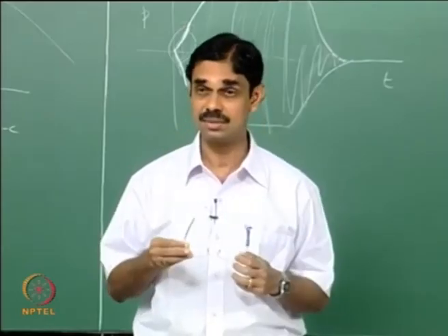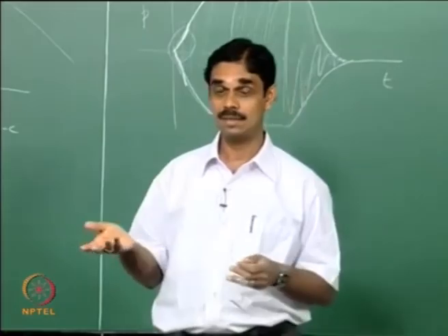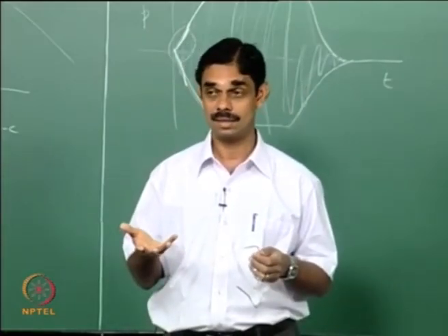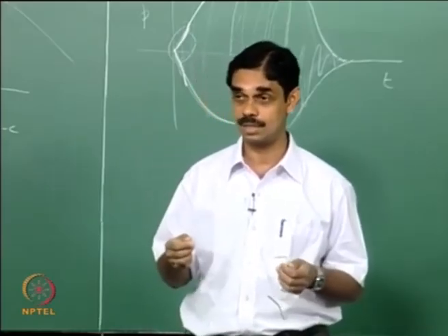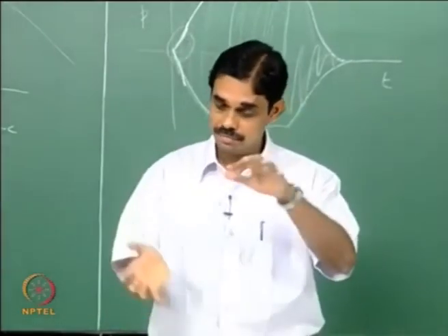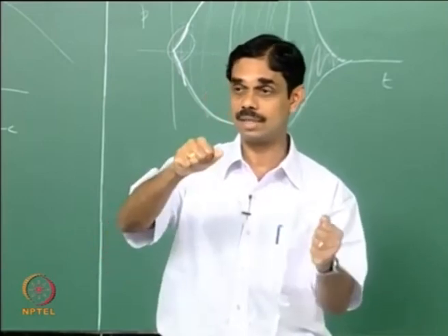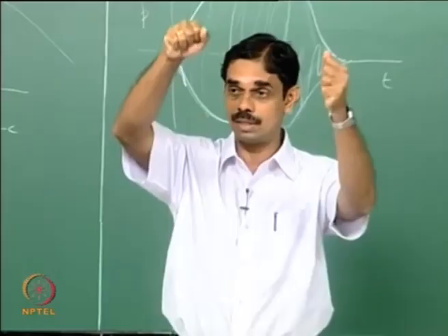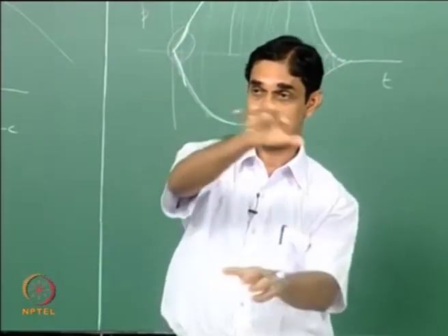Now, where to place the transducers, we would like to measure them at a pressure maxima. So if you have it at the end, then you will always have a pressure maxima, and therefore you will definitely measure the pressure whatever mode it is, if it is a longitudinal mode. But if it is a tangential mode, then you have to put them at different locations, and then you have to see the phase, whether all transducers are going up, all the pressure is going up together, or one is going up and the one is coming up later. Then you have a mode like this.